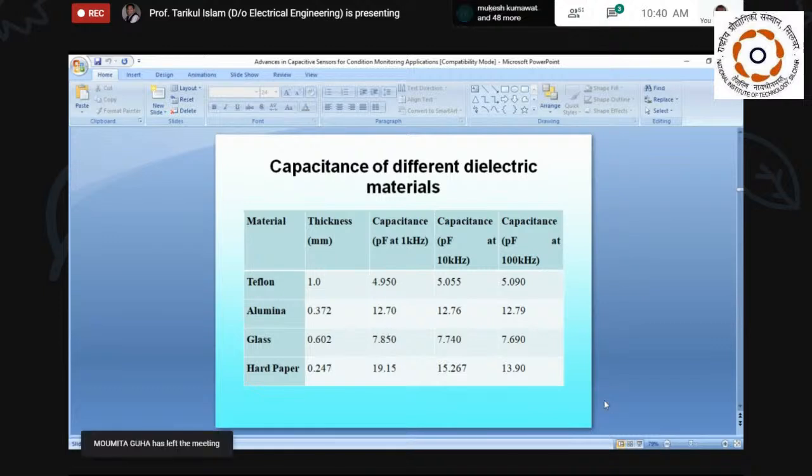It can be interfaced to a PC, then you have the capacitor value, and you do a little calculation, because you should know what the material is, since you are calculating the thickness based on epsilon R. So epsilon R of the material should be known to us. If you use this value, then we can find the capacitor value.